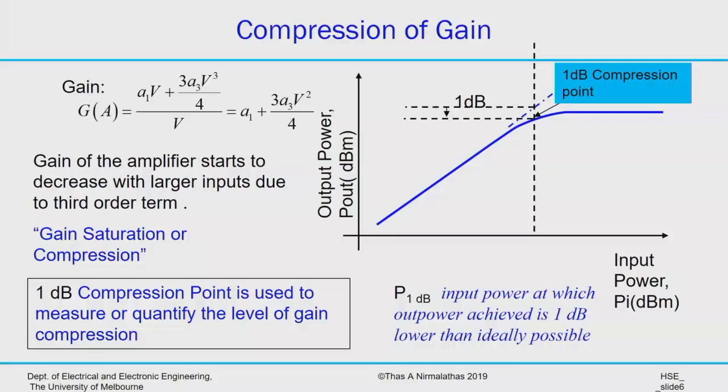All right? So in essence, you will never exceed your input range beyond that point, because unless you don't really care about nonlinearity, you don't gain anything in gain terms, and you create more problems in terms of harmonics being produced. So it's a very, very common specification. If you open up an RF amplifier, when you go home, Google it, you will see a compression point mentioned. That gives you an indication of up to what point I can play with this amplifier. It's an important parameter to know before you start applying a signal, because if the actual power that you need the amplifier to operate at is beyond it, it's not going to work, right? You need to keep looking for a compression point further down.